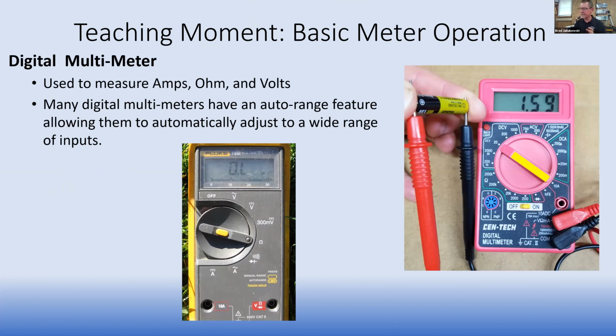And so then, let's make sure that everybody who's got their multimeter with them, let's go ahead and check them out and make sure that they're operating correctly. I've got a couple of camera options that we can do on this one here. So this is our multimeter. The first thing is, let's turn your multimeter on, make sure that it's operating. Okay, you should get 0 or something close to 0 when we first fire it up.